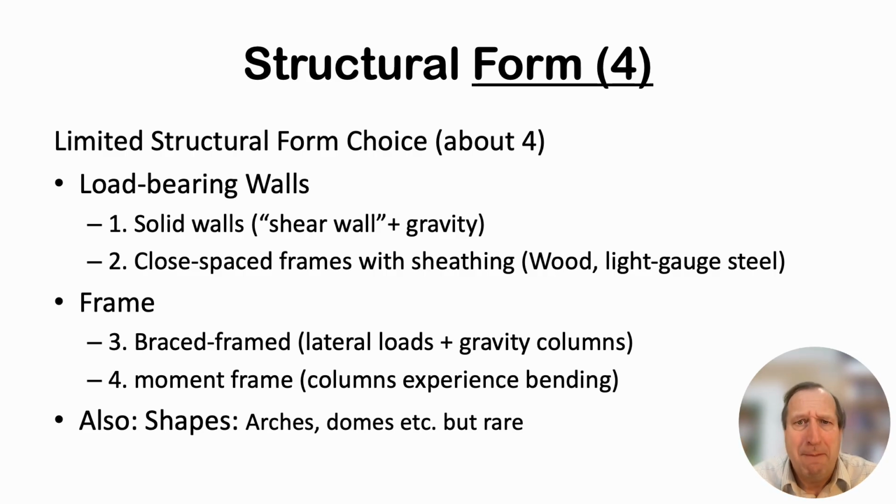But of course, a solid shear wall made of, say, 8 inches of reinforced concrete can take an awful lot of vertical load, and hence it's used for gravity loads as well. Now, when I call them solid walls, I'm doing air quotes around that because we also have a lot of small or medium-sized holes that form in a solid wall, which don't weaken it that much. And so it's still a solid wall, shear wall structure.